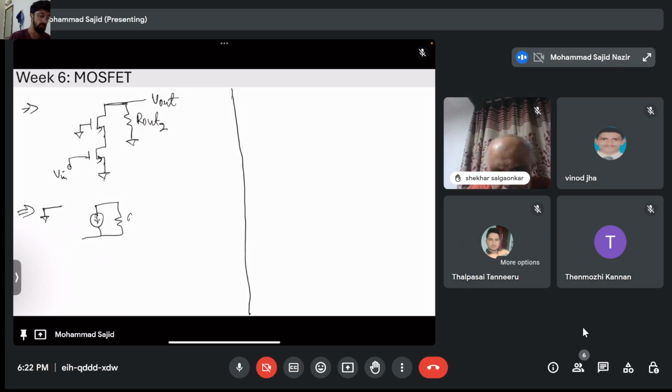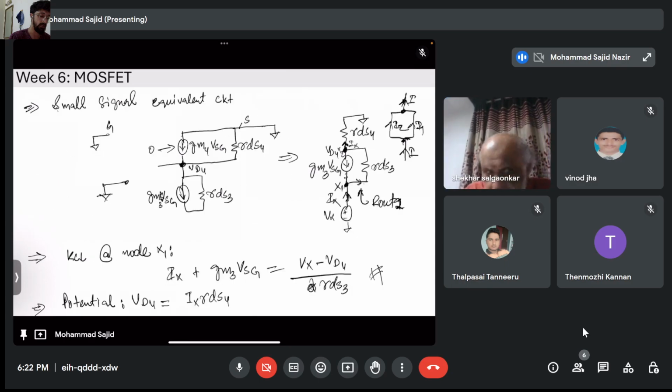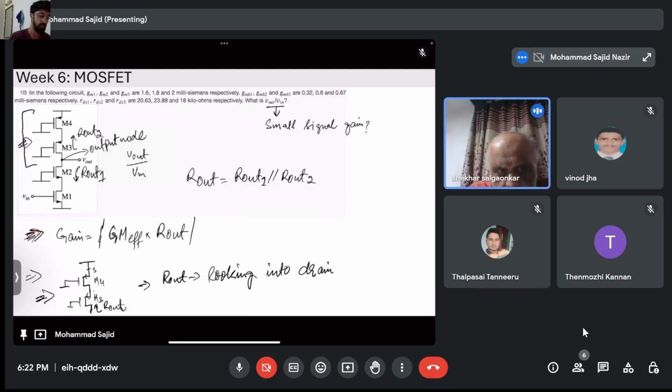Please unmute yourself if you have anything to say. Hello, sir, can I have one question? Yes, please. In the transistor M4, on the topmost, one second. Okay, M4, yes. Now you consider gm4 Vgs as zero, correct? Yes. Why is it so? Because the gate is grounded and the source is also grounded. Okay, fair enough. Thank you.